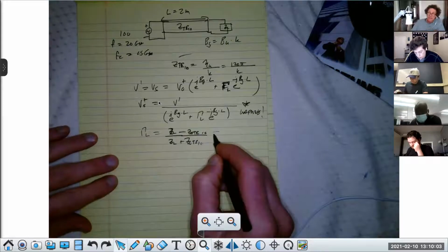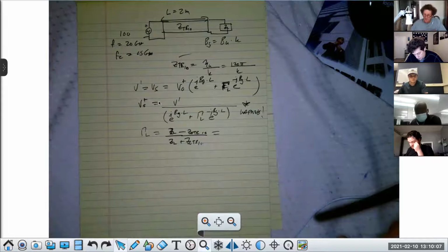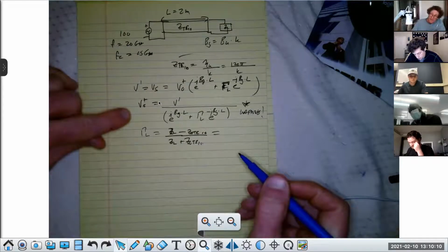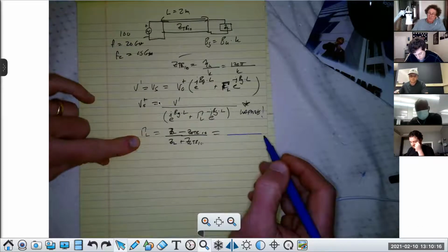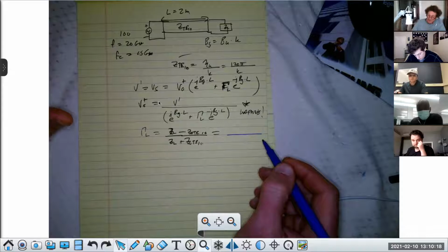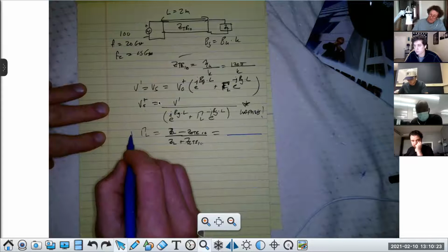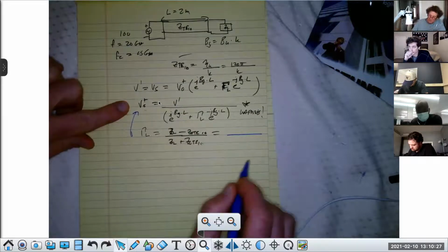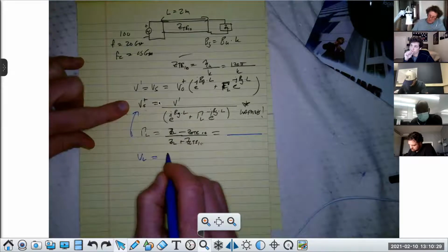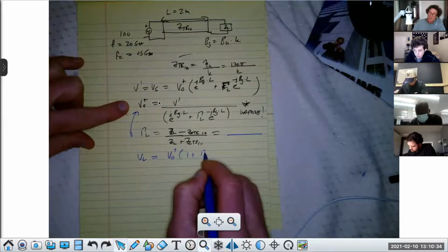All right. I'm trying to put the steps down again. I know you guys have been hanging in there with me, and I appreciate it. Thank you. I got that. I'll be able to get it correct, class. Once I get this, I can get this. I need this first to get that. I know what V prime is. Once I have this, I know the voltage at the load is just going to be that V0 plus times 1 plus the reflection coefficient at the load, right?